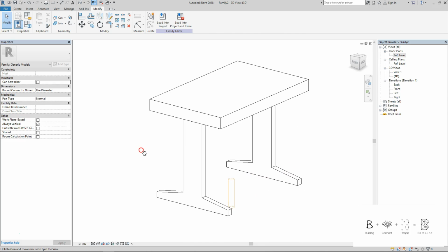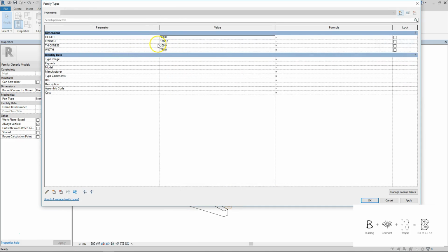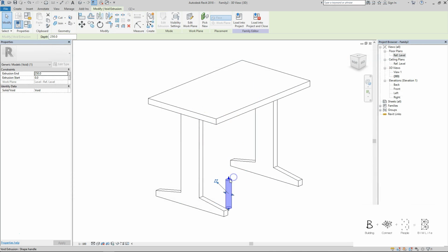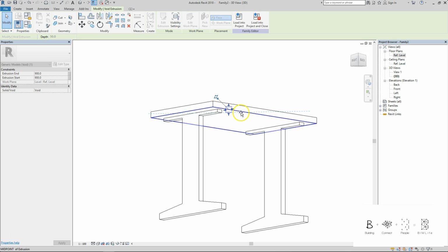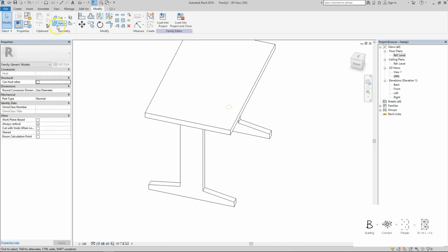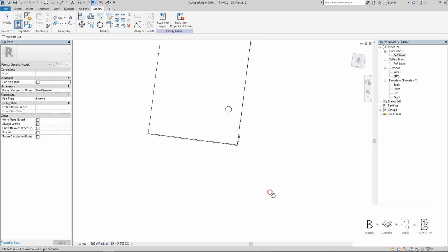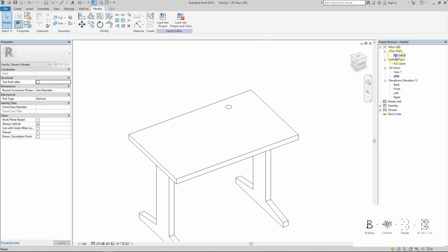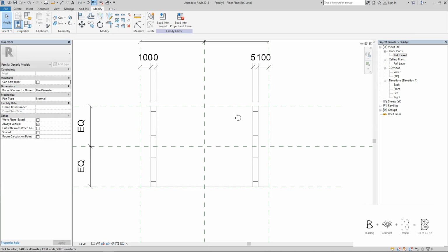And the void, let me see, my table thickness is not correct. My table thickness should be 50. Okay. Let's care about the void again. So I'm just going to drag it all the way up here and lock it. Okay, wait, let me lock it here and drag the bottom to the bottom of the table. Okay, here, bottom of the table, lock it. And I need you to use the cut tool to create a hole in the table. So I'm just going to position the hole because there is a specification that it must be 100 mm away from